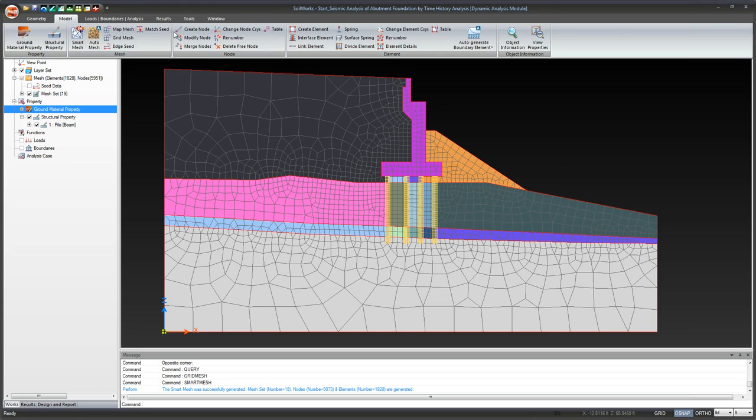In order to create your surface springs, just go to the right here under the element tab and then select, well, actually there are two ways you can create your surface springs. As I said previously in the introduction, when you're creating surface springs for different soil layers, each one will require a different function. So let me open this up real quick.